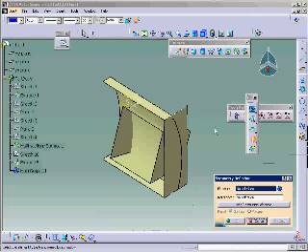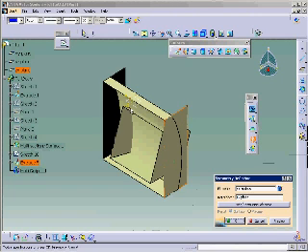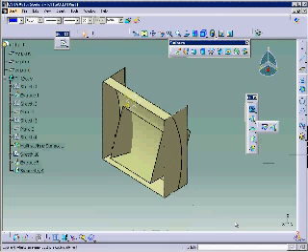Next, you are prompted to select the reference point, line, or plane. Select the ZX plane as the reference plane. The preview of the mirrored surface is displayed in the Geometry area. Choose the OK button. The model, after mirroring the extruded surface, is displayed.